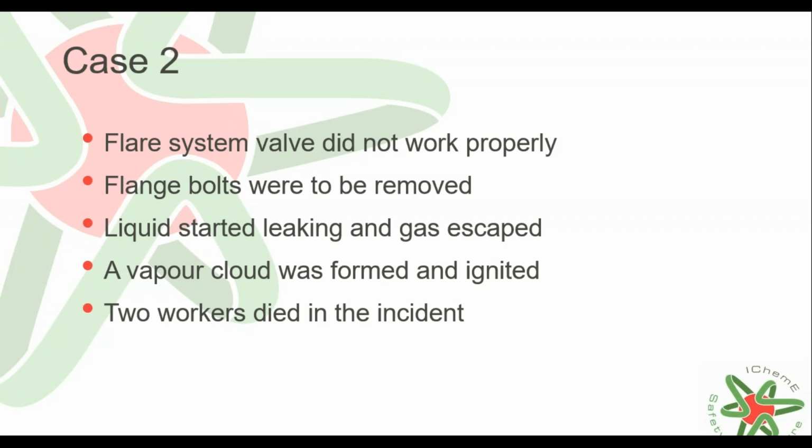Liquid continued to leak as more bolts were removed. And then, as the last bolt was undone and the crane took the strain and started to lift the valve, the spacer suddenly sprang upwards. A large quantity of liquid was released, and a flammable vapor cloud formed and was ignited by the nearby compressor. The 2 workers died in the incident.